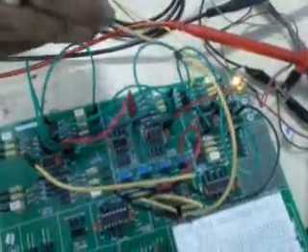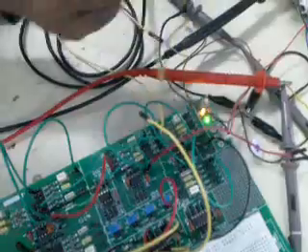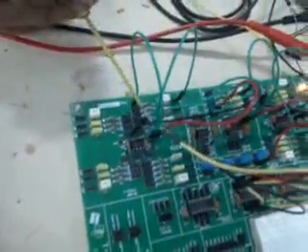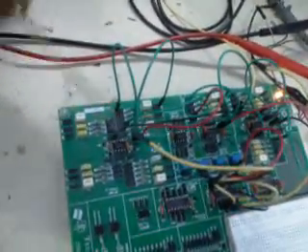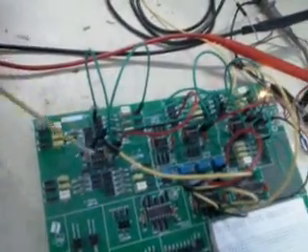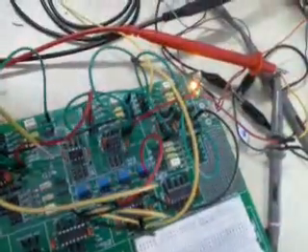Here the input is coming from here, and the output of this input section goes to this op-amp, which is acting as a feedback part. The output of this op-amp is mainly the band pass filter output, which can become the V2 as seen in the earlier case.